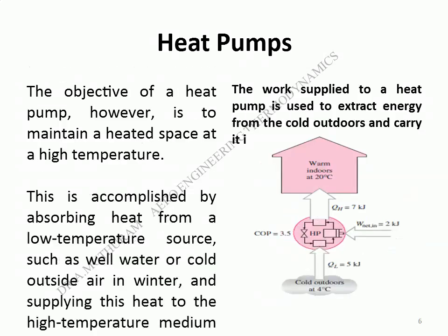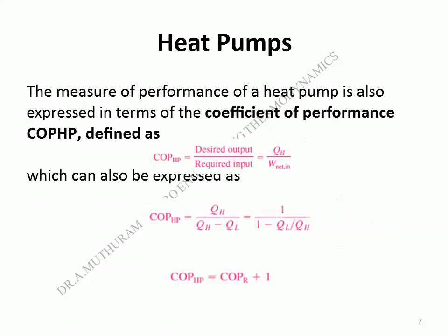The objective of a heat pump, however, is to maintain a heated space at a high temperature. This is accomplished by absorbing heat from a low-temperature source, such as well water or cold outside air in winter, and supplying this heat to the high-temperature medium, such as a house. The work supplied to a heat pump is used to extract energy from the cold outdoors and carry it into the warm indoors. The measure of performance of a heat pump is also expressed in terms of the coefficient of